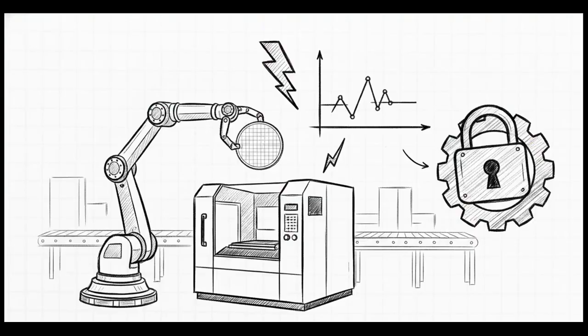Because of this reality, your manufacturing execution system, specifically robust platforms like Critical Manufacturing MES, absolutely must own this space. This is your operational quality execution backbone. It's capturing low-latency physical data directly from the tools. If a process drifts out of bounds even a tiny bit, the MES instantly calculates real-time control limits and fires off automated tool interlocks to stop bad product right in its tracks.